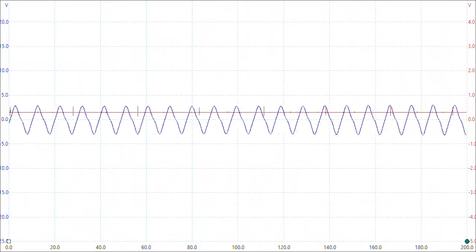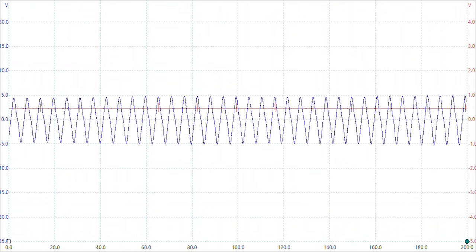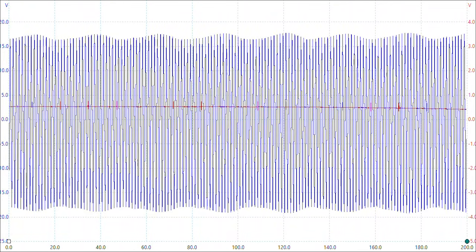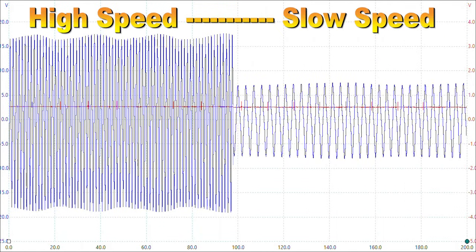This live analog speed sensor signal demonstrates the increase in frequency and voltage intensity as the speed of the vehicle increased. Viewing the slow and high-speed waveforms side by side makes the differences obvious.